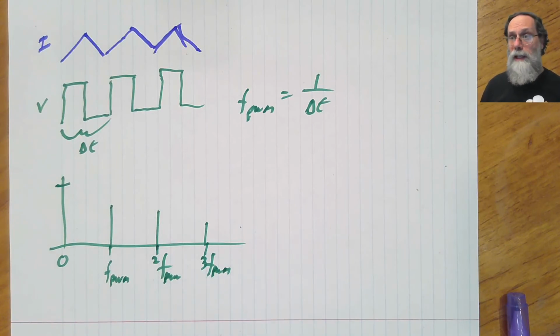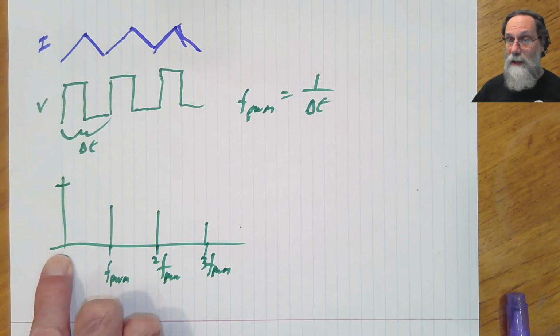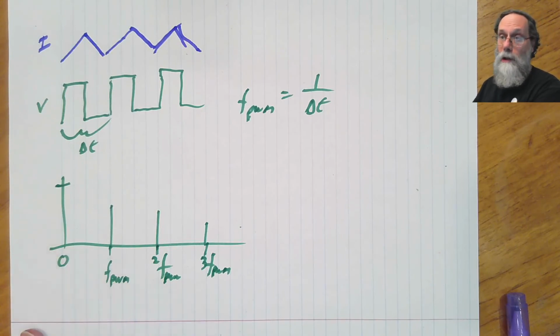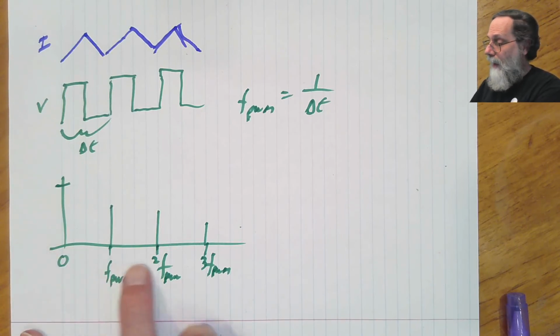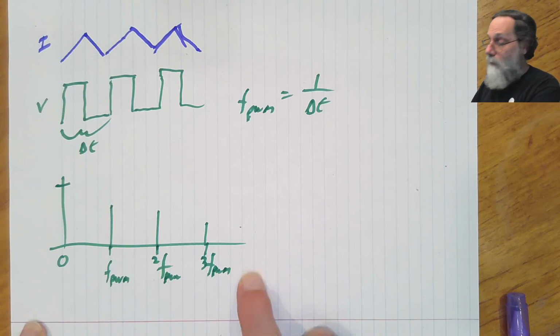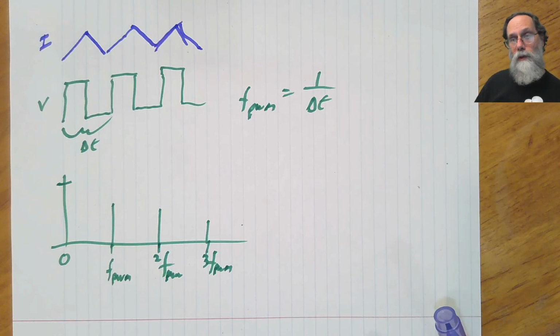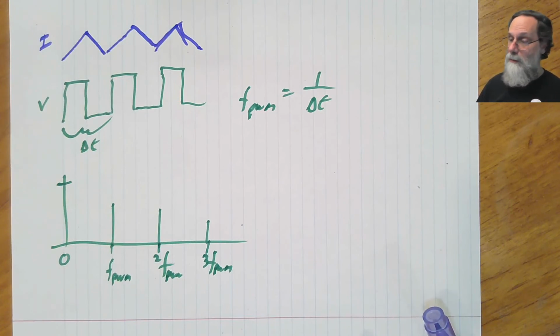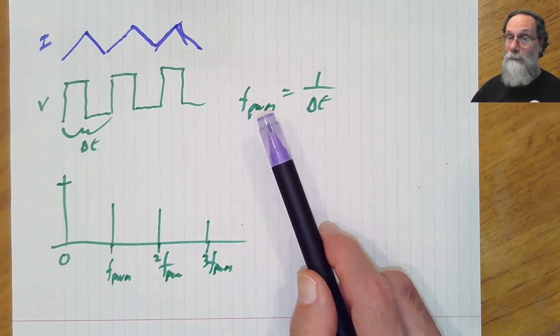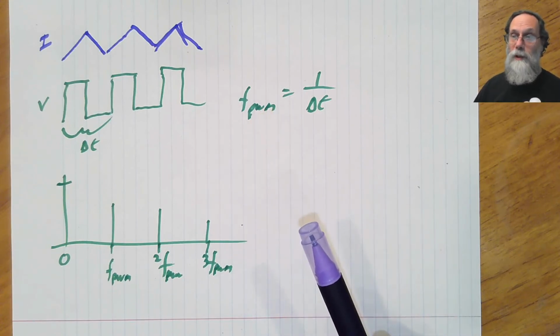If we wanted to get just the signal, which is all at low frequencies, and get rid of the high frequency stuff here, well, notice that this was a discrete time. So we've got the standard Nyquist theorem results that says anything that's less than half our sampling rate, so less than half of F_PWM, is the signal that we really want.